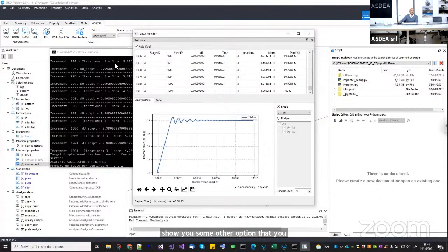Now, this one and this one are the same. So let me show you the second one, the 2D one. Okay, now let's say you have to create a contact element between two bodies. Okay, now this one is the master body, the coarser one, and the finer one is the slave body. Okay. Now, first of all, in this kind of situation, when you have different meshes, you cannot create a node-to-node contact. Why? Well, because here I could create a node-to-node contact here as well, but I cannot create a node-to-node contact here in the middle because for this slave node, I don't have a corresponding master node. So using standard node-to-node contact.